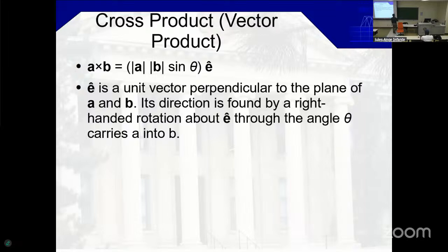So if this is 3 plus 479.56, then they will make sure to have a stake at 3 plus 480, exactly, right? And then they will have another one at 3 plus 500 if they're going by 20 meters, or if they go by 10 meters, 490. Let's say it's every 20 meters. So those will be stakes that will be marked on the project.